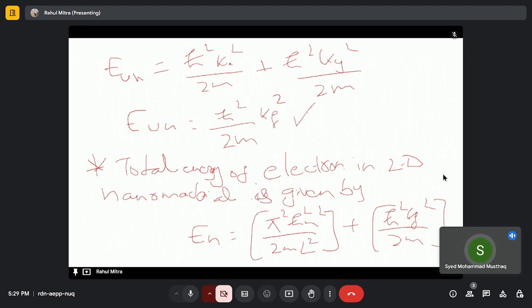Since the electron states are confined along the nanoscale thickness, the electron momentum is only relevant along the in-plane direction, right? And also, for example, scattering by phonons and impurities occurs mainly in-plane, leading to 2D electron conduction. However, for 2D nanomaterials with nanocrystalline structure, we have a large amount of grain boundary areas, and also interfaces, right? So that can lead to more electron scattering or phonon scattering, which decreases the electrical conductivity.